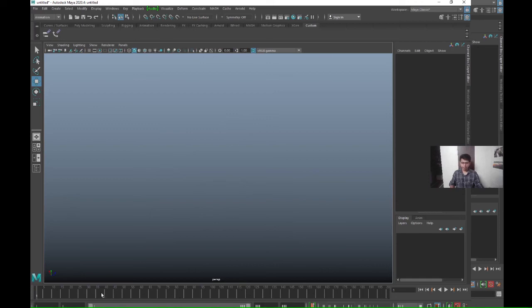Now this is the time slider, where you will animate, whatever keys you put you will see here in the time slider. You can adjust the time slider. This is what we call the time range slider. You can just set the range, whatever frames you want. These are the number of frames. You have 24 frames in 1 second. Suppose you want to do animation for 4 seconds, you can just type here 96. So this is 4 seconds. And you can adjust it here as well.